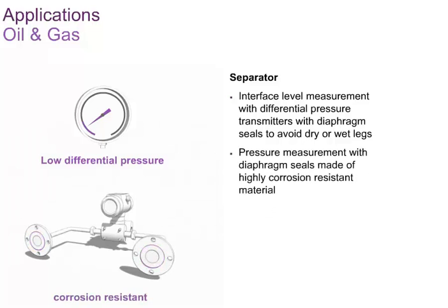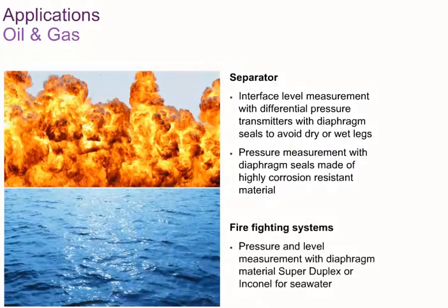Due to the measured media, the parts in contact with the medium need high corrosion resistance. The firefighting system operates with seawater, which requires seawater-resistant material for the diaphragms, for example, super duplex or Inconel.